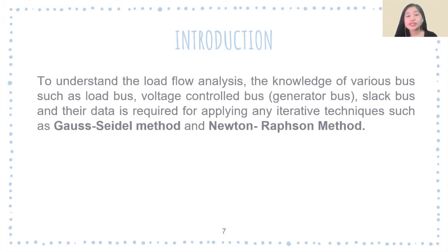Furthermore, to fully understand our load flow analysis, knowledge of the various buses, such as the load bus, the voltage controlled bus, or what we call the generator bus, and the slack bus, and their data is required for applying any iterative techniques such as the Gauss Seidel method and the Newton-Raphson method.